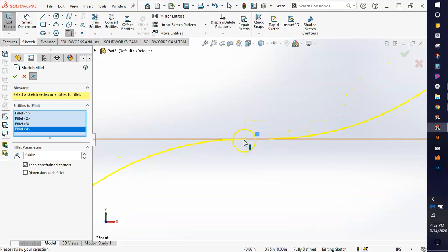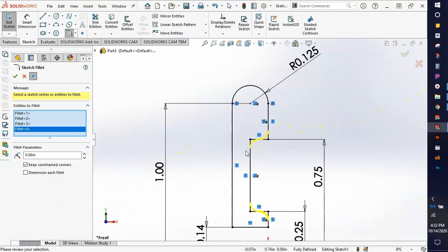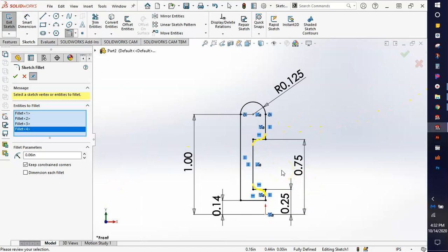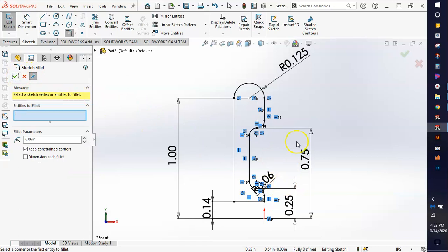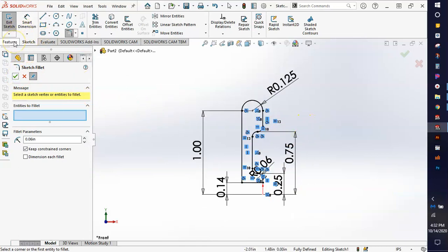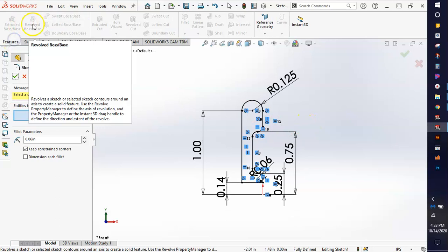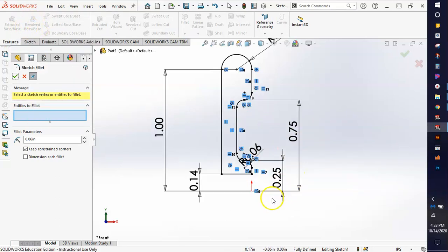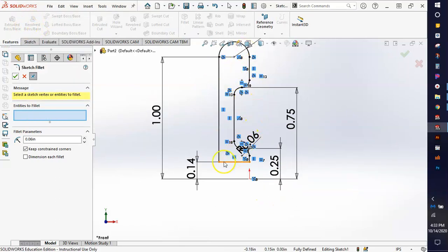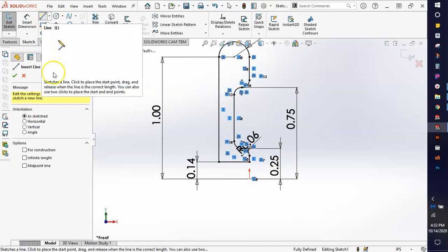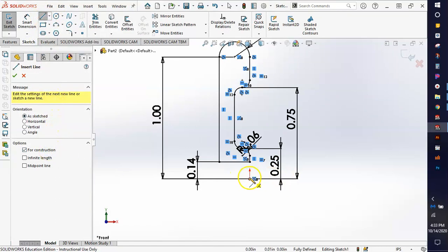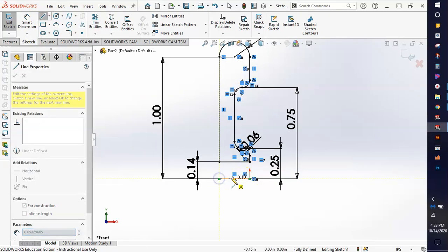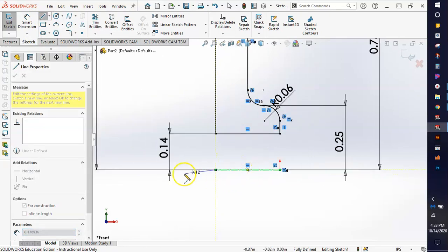It would be nice if both of those matched up, but sometimes SolidWorks gives you kind of a warning when you have a perfect radius that connects into the next one. So I hit the green check. There's my measurements. Everything's good. It's fully defined. But most people would try to go over to revolve. The only problem with that is we don't want to revolve it off any of the lines we have drawn. We want to revolve it around the origin. So we need to actually sketch a line there yet. Get your line tool and a construction line, and I'm just going to simply click on my origin and draw over. So that's the central axis.